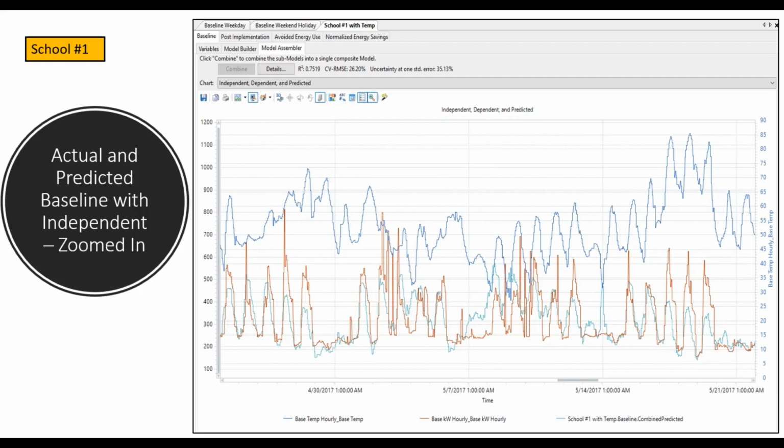You can also see, right where the third major hash mark is, the temperature drops, and because of that, the baseline model, the teal, comes up and kisses the temperature, because the model thinks, okay, because it got cold, we must be using a lot more electricity in this electrically heated building. But the building must have had it locked out, and so in the actual case, nothing happened. So you can see the flaws in the model, but also learn some things about how your building is behaving.